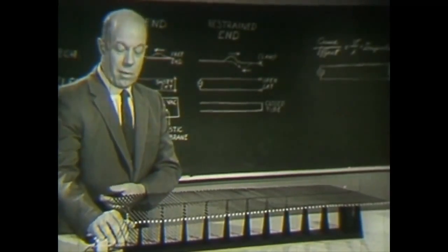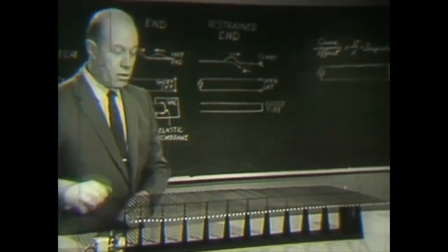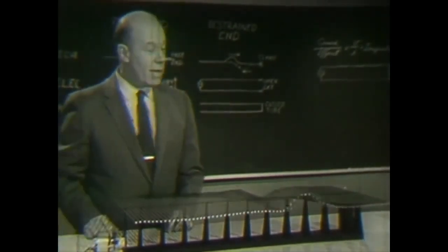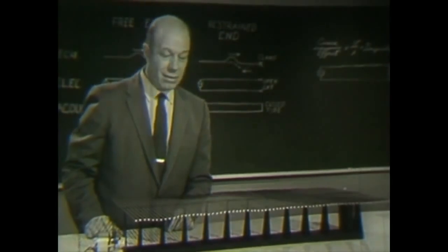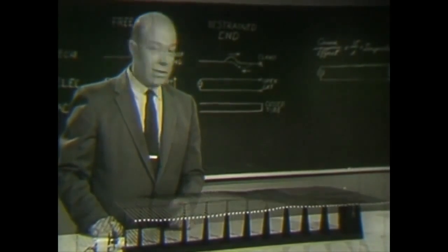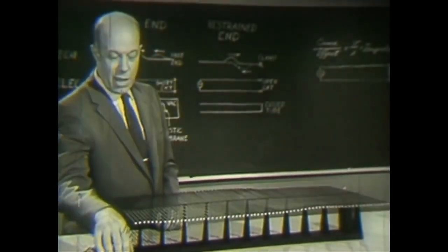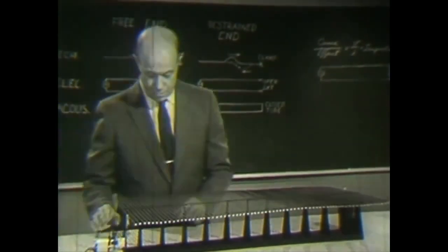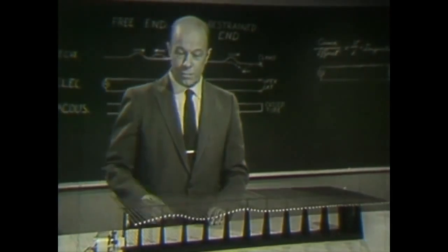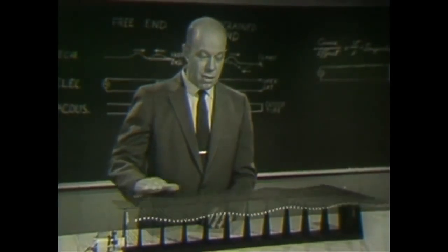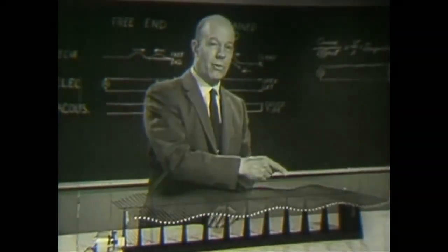When this adjustment is properly made, the dash pot absorbs all the wave energy that travels down the line, and as you can see, hardly any perceptible reflection takes place. Now, instead of using single waves, suppose we have a look at this behavior with a train of continuous waves. Here you see such a train of waves traveling down the machine from the generator to the load and disappearing into the dash pot.